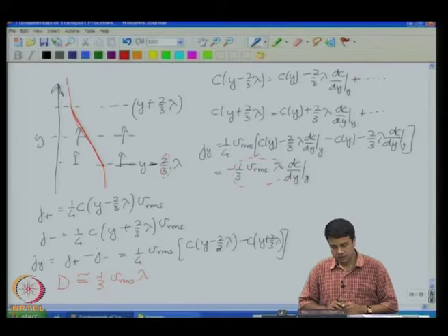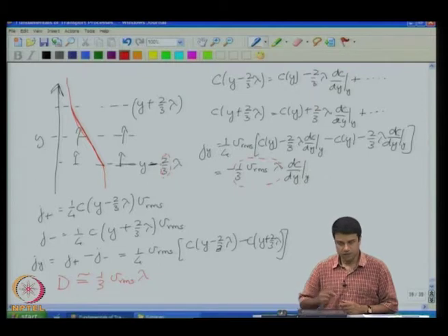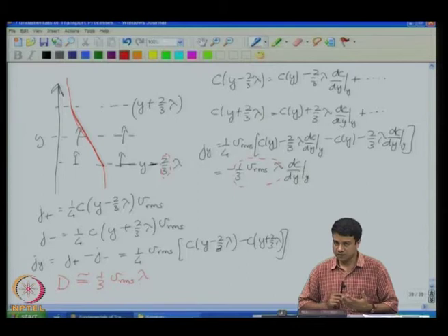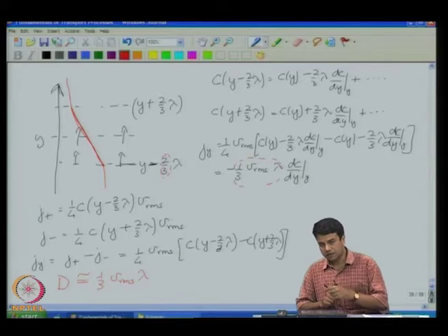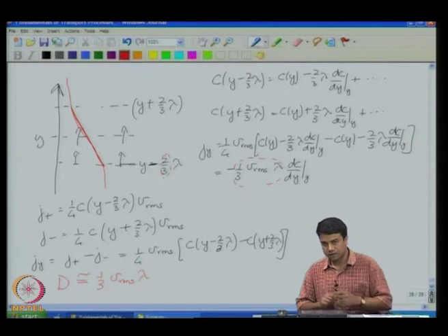Two things. One, the flux depends upon the variation of the concentration with respect to position. Therefore, there is a diffusive flux only when there is a variation of concentration with respect to position. This is called the gradient of the concentration field. I told you that Fick's law relates the flux to the rate of change with position of the mass density, the concentration.